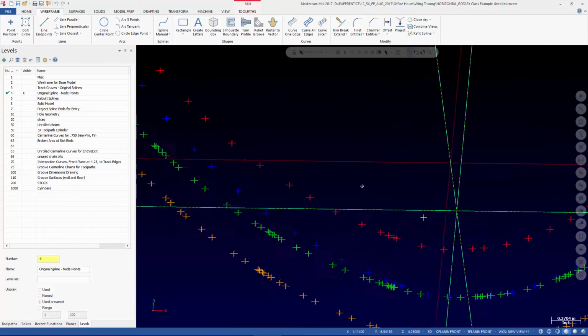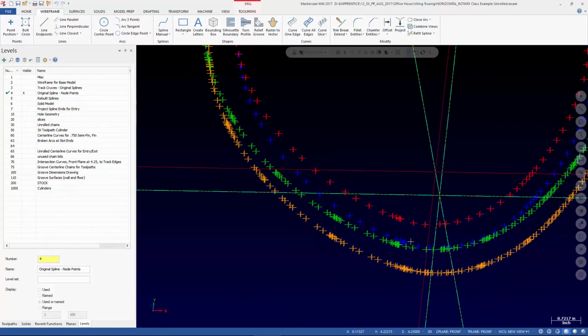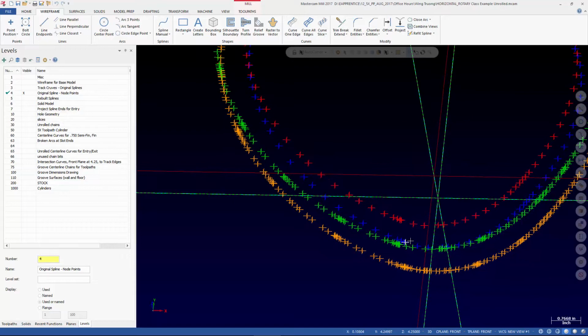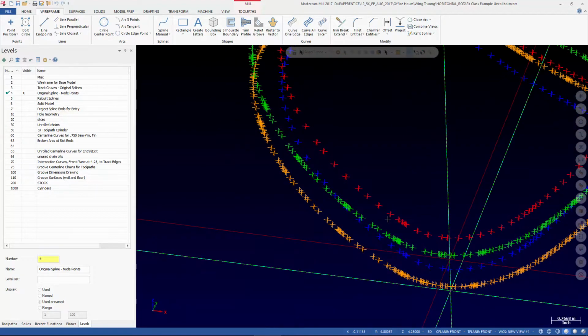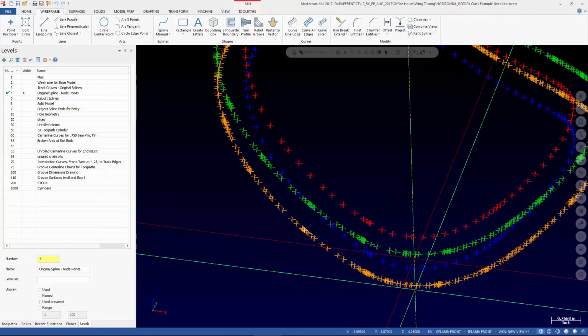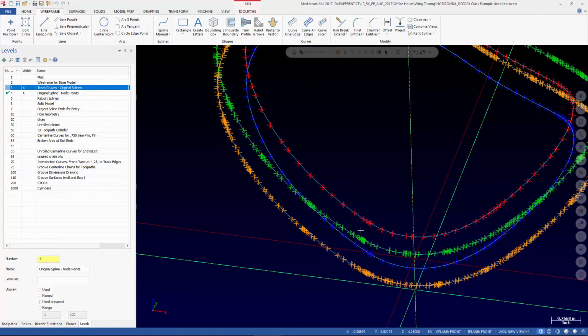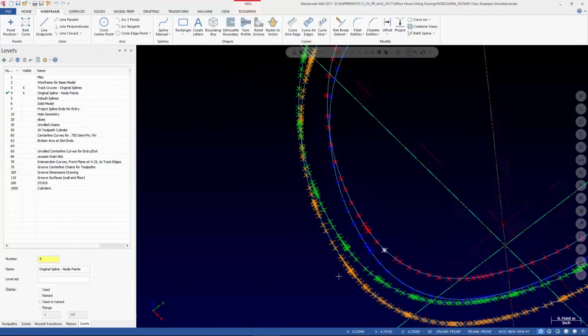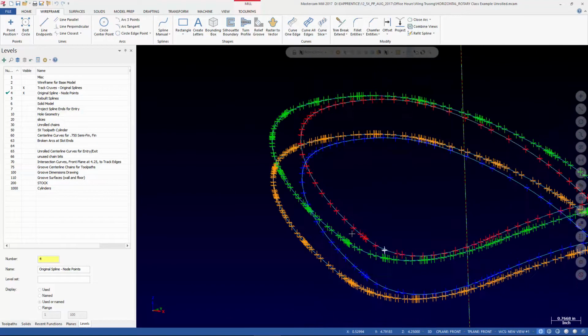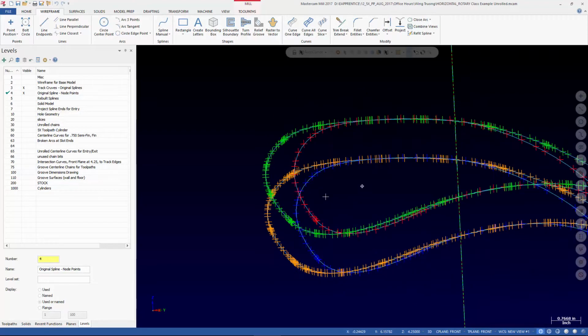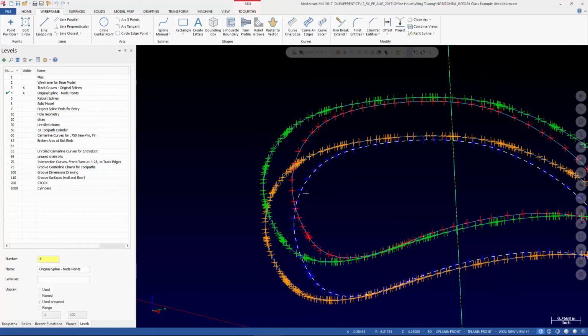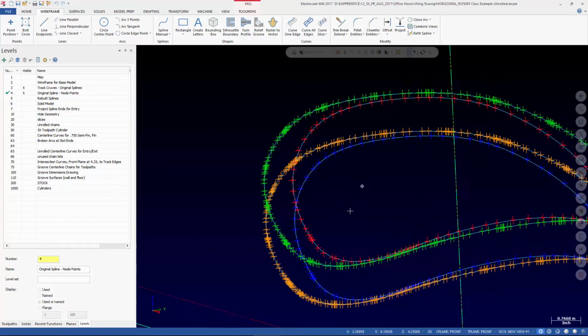The reason I bring that up is because we're not driving lines and arcs. The geometry that we've got to work with is created based on whatever geometry was given to us. Right now, when we look at the track curves, that's spline data. And a spline is a mathematical curve that flows between control points and uses knot vectors to determine how much those control points pull the geometry or push the geometry.